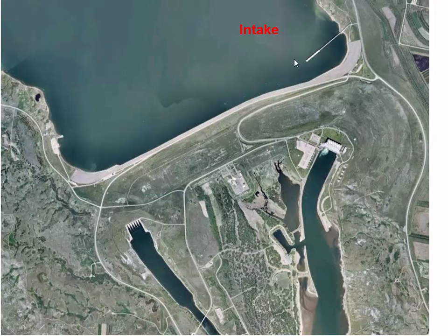It's an earth dam, and they generally will have the intake a little bit away from that, because if you have water going into a pipe, then it can cause localized high velocity, and then that could scour the material around the dam, which would be bad. You don't want the material from the dam going into the pipe, because the water's accelerating as it goes into the pipe and has some energy. And so they put a pipe into the water and suck the water out that way.